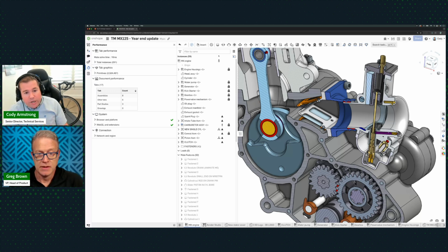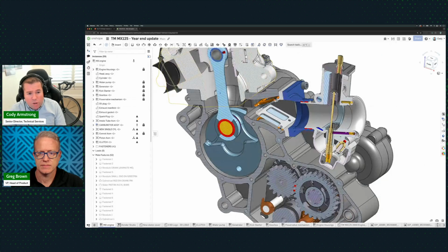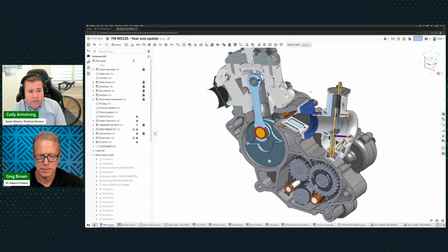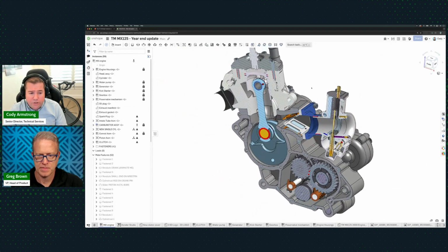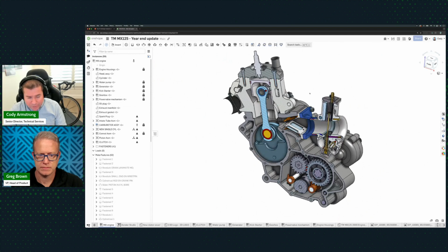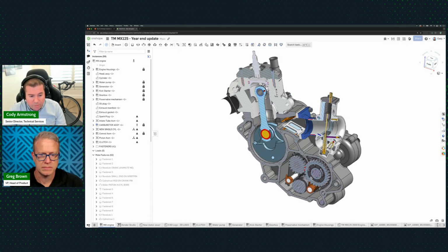But again, to stress, if you're in that world of building big assemblies, this is a tool that can have a dramatic impact on your mate solve time and really improve the overall performance of your assembly. So one that I really encourage you to take a close look at as you start to build those big assemblies. All right, so that is lock position, and more importantly, the ability to follow that named position, something I think a lot of users will really appreciate.